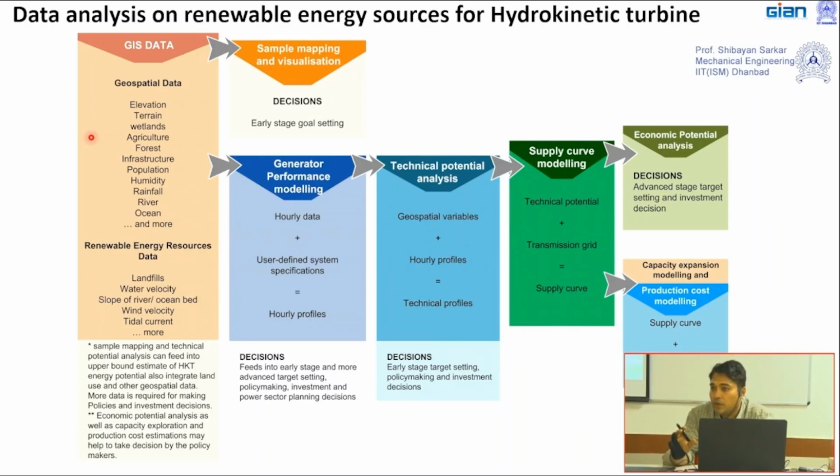So based on the nature of the land use, the ultimate discharge coming out of the river will change. That type of hydrological or water resource analysis can be done through GIS data as well as weather data. In India, IMD provides grid based data. In a particular grid, at some degree resolution, they provide precipitation as well as temperature as well as relative humidity data.